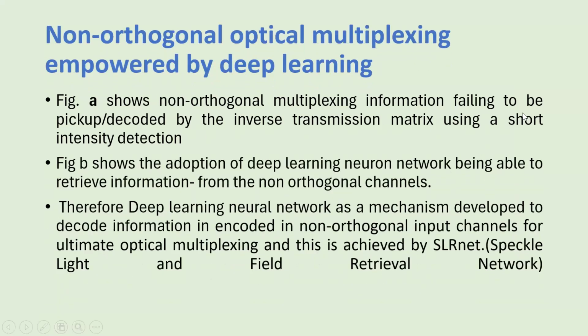So this has been the explanation of the previous slides, how the inverse matrix fails when you apply non-orthogonal optical signals or non-orthogonal optical light fields, how that transmission matrix fails to pick up or to decode the information brought by that single signal from the MMF cable.